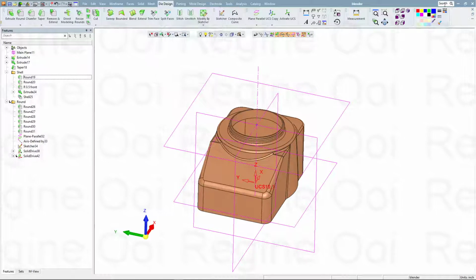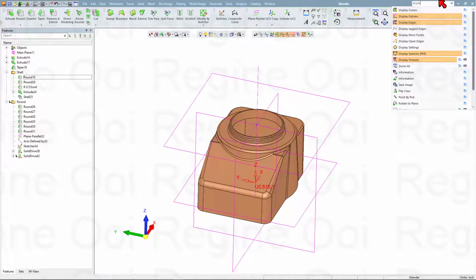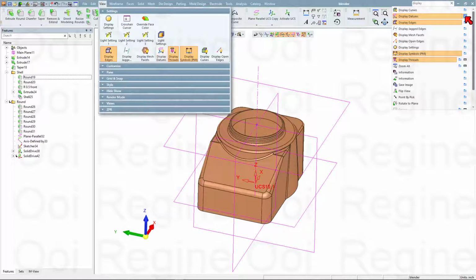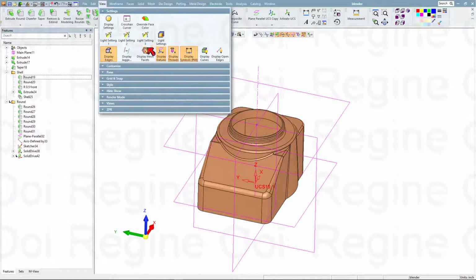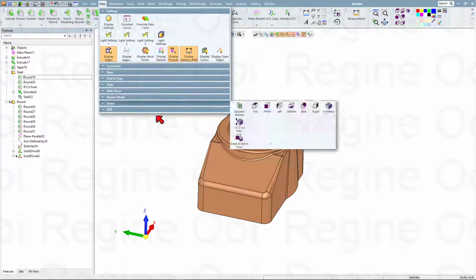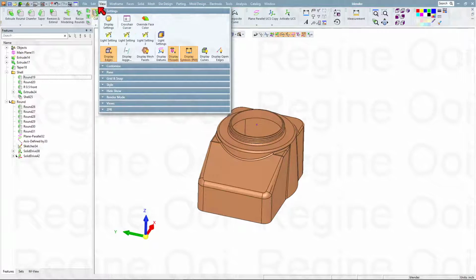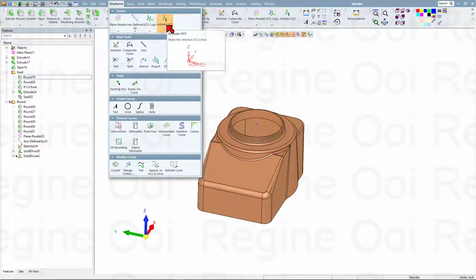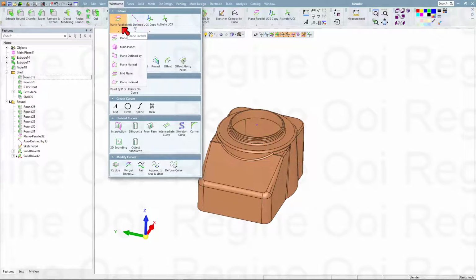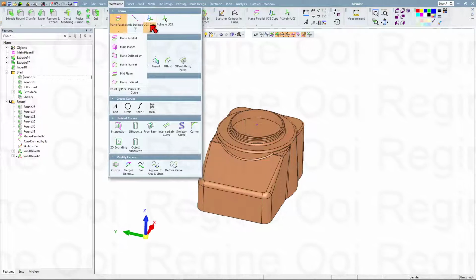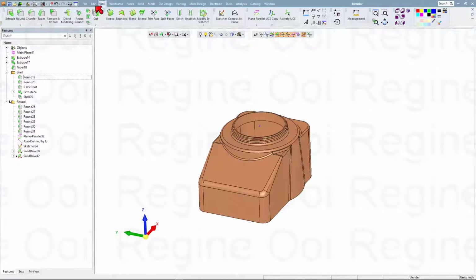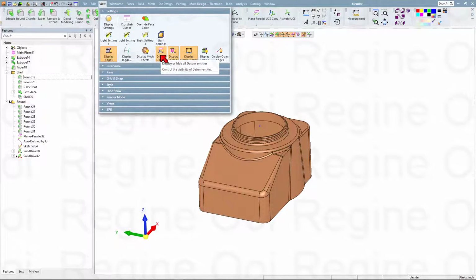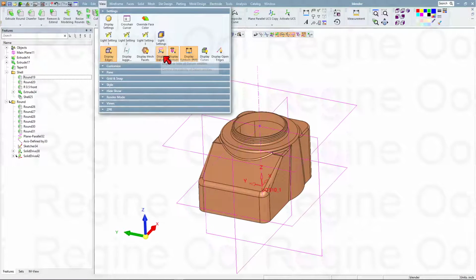or you can search display datums, show me. Okay, under this view setting display datum, to turn off all the functions related to the datums, UCS, axis, and also the planes, which are under these datum groups. If you want to turn it back on, just go to this view setting, display datums, to turn it on.